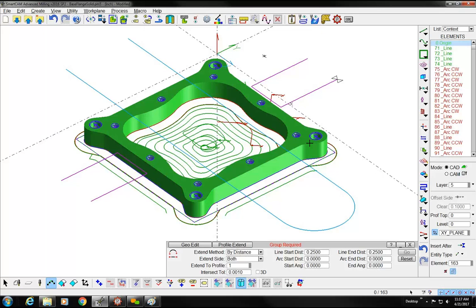Great. Tom says, you use show path to check the tool path, paused it, and then removed the previously drawn path. When would that be beneficial to use exactly? Well, if you wanted to focus in on one tool, or imagine if your roughing pass was just a small step over, a small depth, and had all kinds of tool path in there.